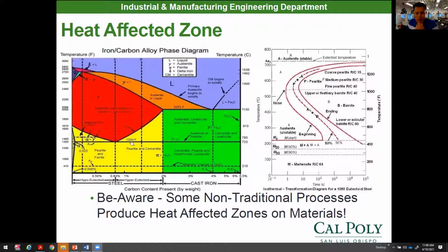But when we're above the austenitic range here for steel, let's say we were right up in here in the steel, and let's say we had 0.83% carbon content. We go to quench it. We end up with different grain structures in there. And if this happens during the manufacturing processes, we may end up with properties that might hamper our design or might end up causing the part to break or prematurely fail in actual service.